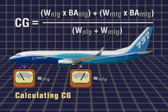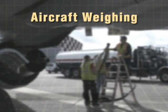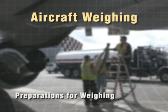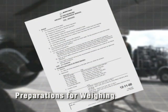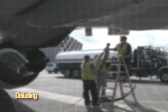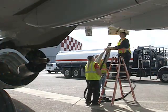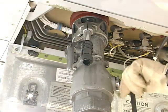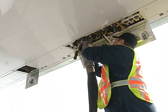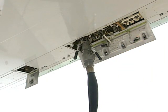Now that we know about the datum and balance arm, we are ready to determine CG. The number of scales differs depending on the model of the airplane. In the case of your 737, we use one scale under the nose gear and two scales under the main wheels for a total of five. But for the sake of this discussion, consider all the main gear scales as one. You will also need to know the balance arm for the point of contact between each scale and its landing gear. You then multiply the reading at each scale by the balance arm for that scale, add the results together, and then divide that sum by the total weight.